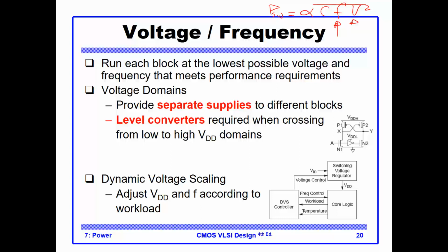Another thing, for V squared here, is to use multiple voltage islands. Multiple voltage islands means that you have different voltages in the design, where for instance you have circuits that work off 1 volt and circuits that work on 0.8 volt. Typically the 1 volt circuits are the fast circuits, and the 0.8 volt circuits are the slower ones, which can afford a lower voltage.